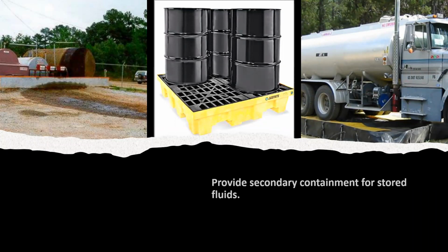We're looking at on the left here. Clearly, this is not a well-contained area. Looks like we've got a leak out of one of our above ground storage tanks. And it's possible that that leak is contained within the berm. But the other issue then is that our fueling stations here must be leaking. So either it's coming out from beneath the bottom of the berm or the fueling stations themselves are dripping out.